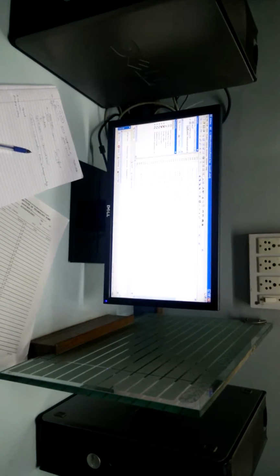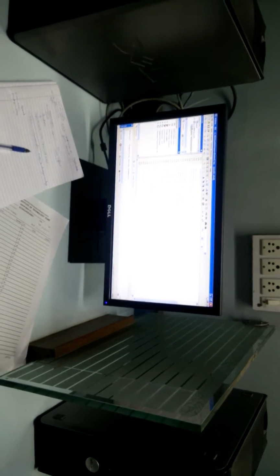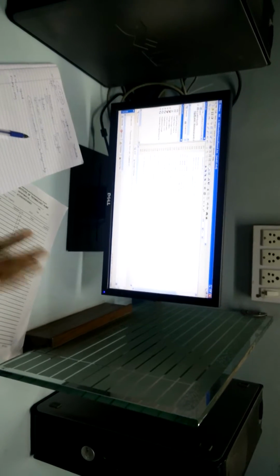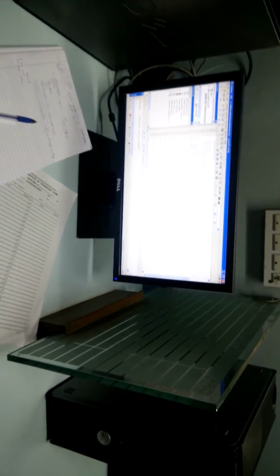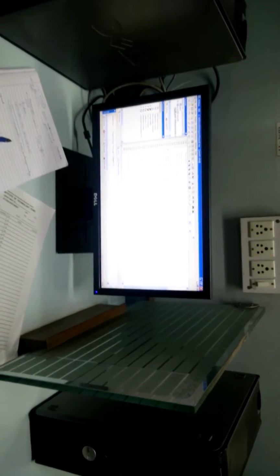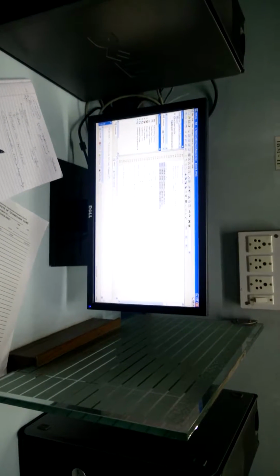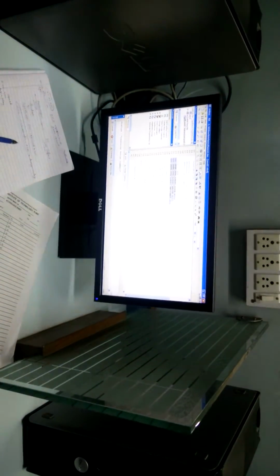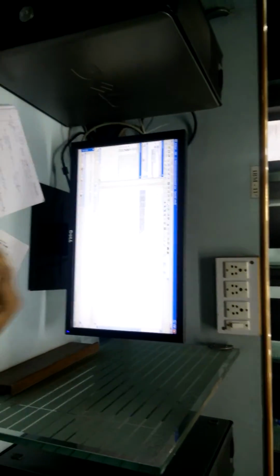This is the topmost entity, or topmost block, in VHDL. It contains everything related to your VHDL code. So the name of the library that we are using is IEEE. Then these 3 lines indicate packages. Inside this library there are different packages available. Now, according to the sequence, you can visualize that